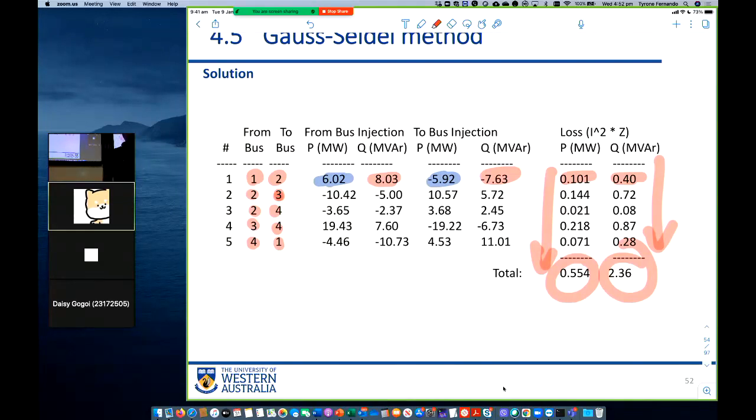You have these numbers here. So calculate all the voltages at every bus. Right? Calculate the power flows out of each bus, power flows into each bus. Calculate the line losses, active power, reactive power. Sum all the load consumptions, active and reactive power. Sum all the generator active power and reactive power generation. See if it all balances out, because if you've done the calculations right, it should all balance out.